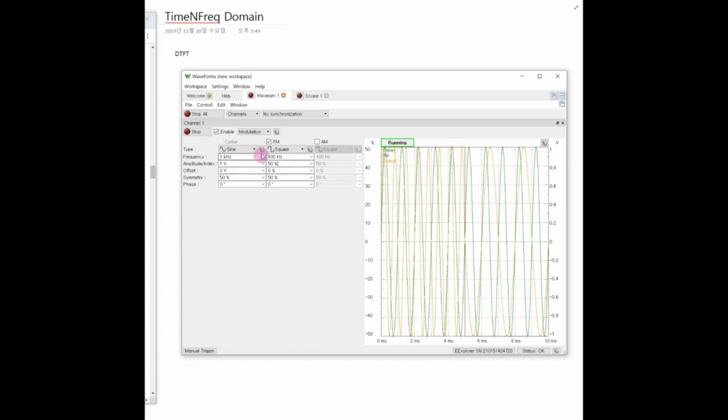So if I take 0, then in that case the red line frequency is 500 Hz. If the data is 1, then that is 1.5 kHz. That frequency spectrum difference is very big. So I'd like to change that one to 10%. 10% means that if the data is 1, then 10% of the carrier frequency, that is 100 Hz, so that is 1.1 kHz increased. If I take 0, then 10% of this frequency is reduced. That is 0.9 kHz.